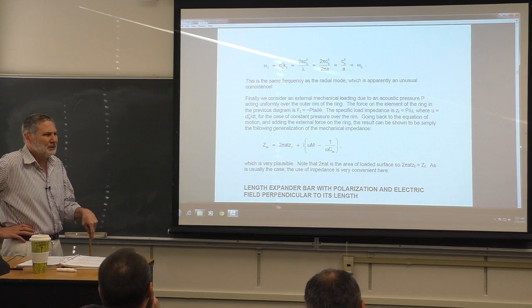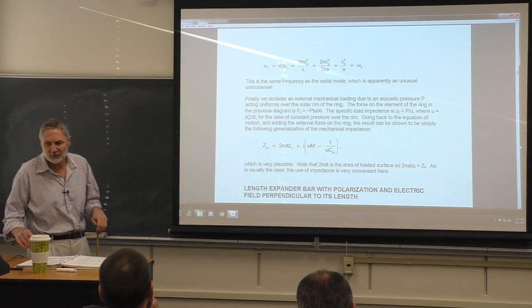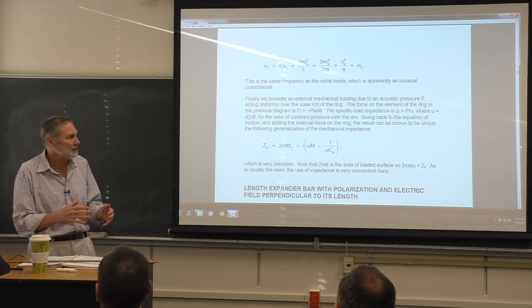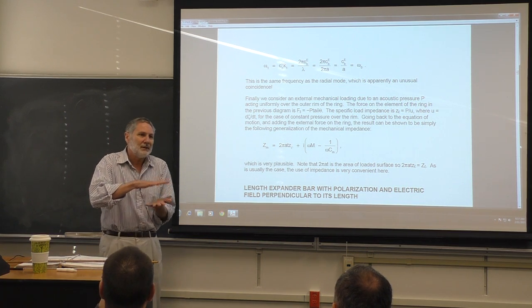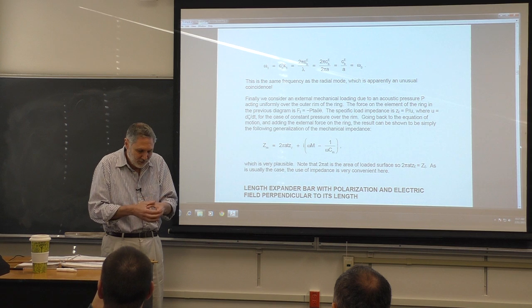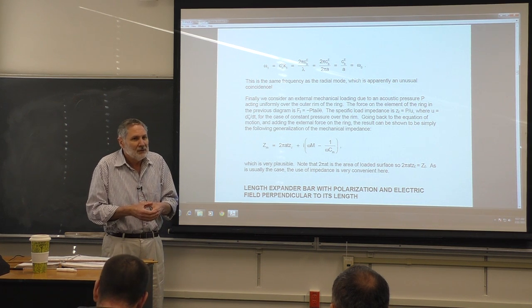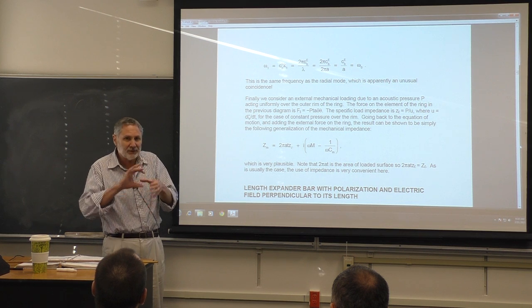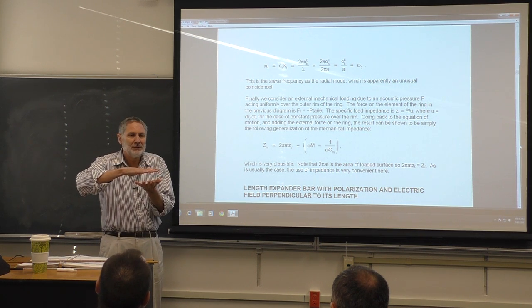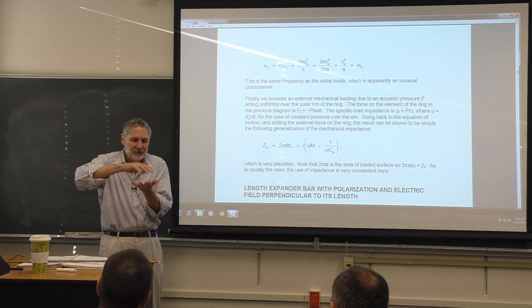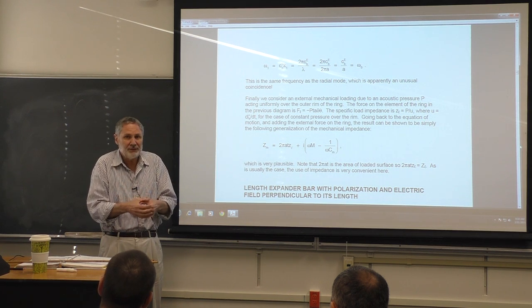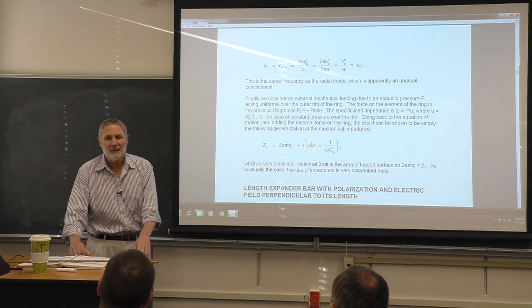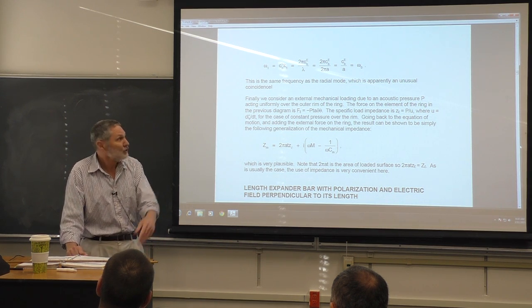Now, it's important from a practical point of view, because suppose you actually had a ring here, and that's, again, the bottom line of this course, real transducers, and you're driving it, and you start to get near this resonance. What's going to happen in a real system? Remember, you're driving it electrically, right? So you might think, theoretically, I'm driving it electrically, it's just going to resonate. And then I can go above resonance, and then the amplitude is going to go down. That's not what happens in real systems. You're going to excite this mode.